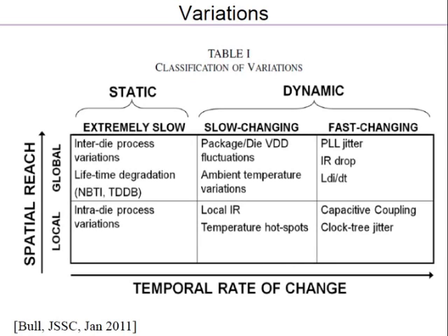That is called intra-die variation. Within the die itself there is variation, and across dies there is variation. Same process, same chip, you take the same AND gate and make another copy somewhere else, it will have a slightly different characteristic. You are manufacturing the chip and the AND gates are fabricated.